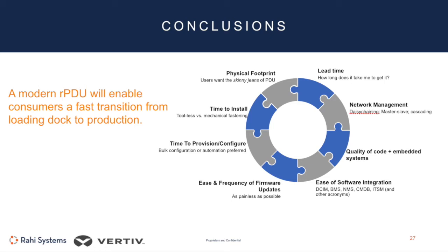And I think we've time for one last question, and that is, what percentage of 240 volt, 415 volt international power are you seeing in the US market? As I mentioned in the presentation, we're seeing some large users go this route for some of their purpose-built on-premise data center facilities, if you will, because they're building at such a scale that the 2 to 3% efficiency gain from going to that higher power distribution actually makes a meaningful difference to them in terms of efficiency.